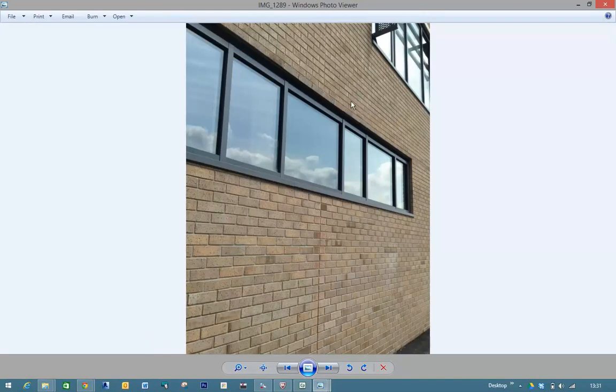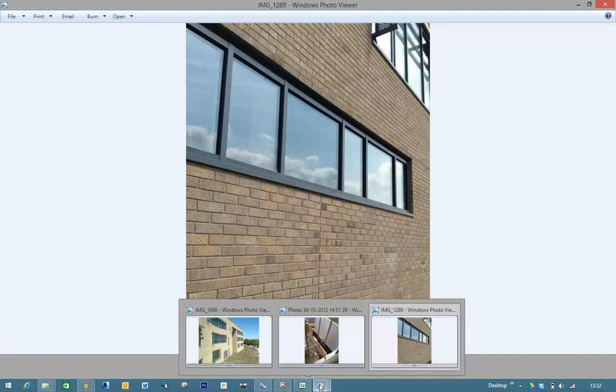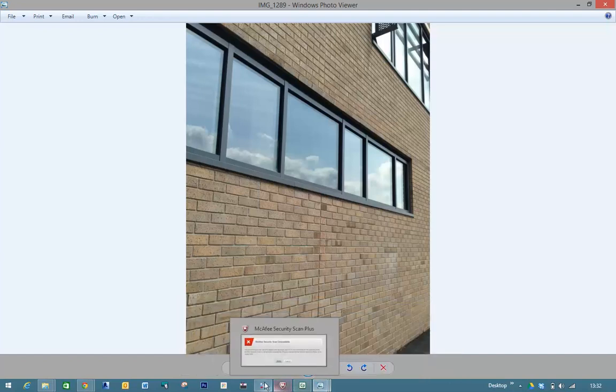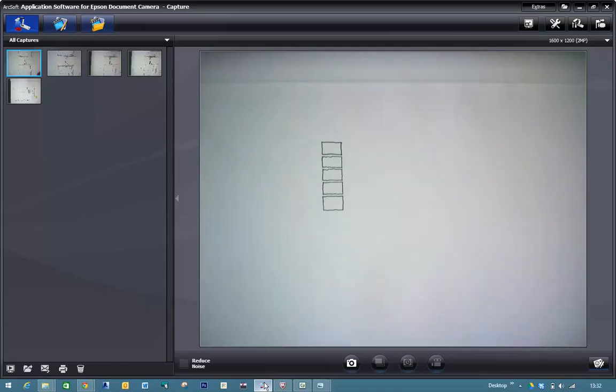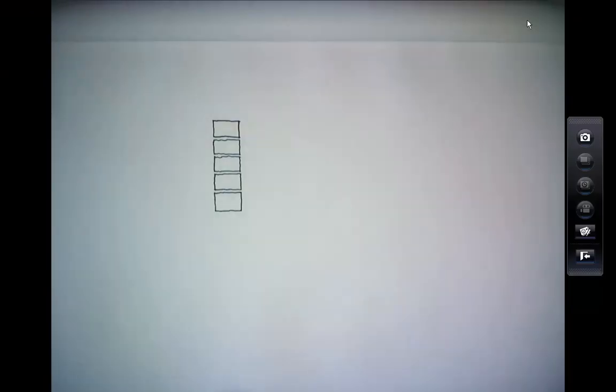It's just a kind of floating brickwork. And when you look at the size of the windows, can you imagine the size of the concrete lintel you would need to span that window? It'd be enormous, okay? So we're not doing that. This is not load-bearing brickwork. It's brickwork held back to a frame.